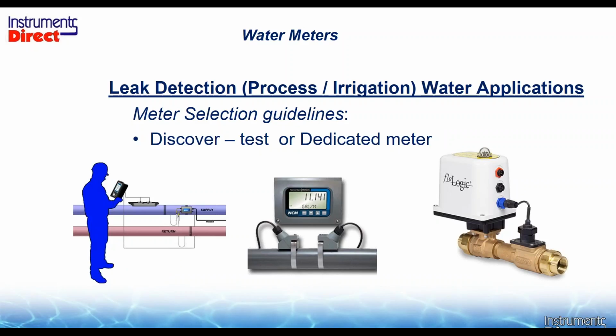So one thing we needed to know was how much water we're using, and one of the ill effects, as we pointed out earlier in the discussion here, is leak detection. Leak detection is another interesting point, and it's a matter of what's practical and not practical. Again, it's all about volumetric flow or velocity of flow, and there are some cases there. So that 10-inch pipe we looked at earlier, if you had a leaky toilet hooked up to the 10-inch pipe there, depending upon the flow meter, if you had a traditional flow meter, you wouldn't detect that.